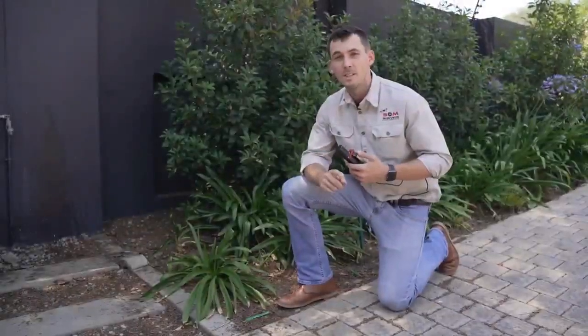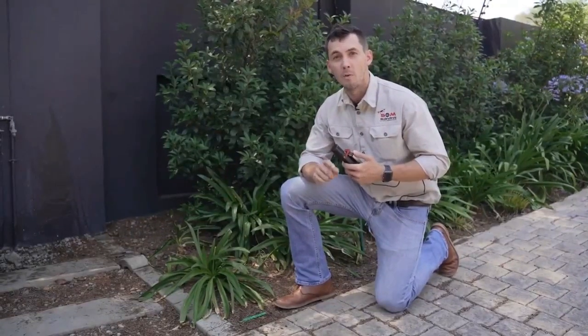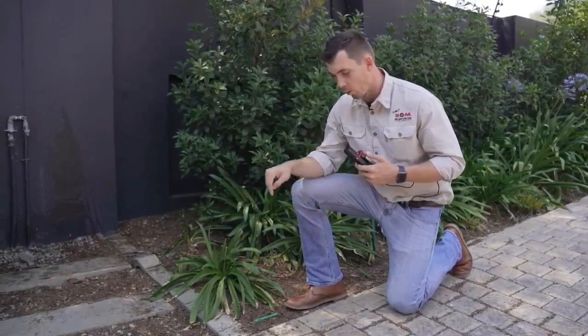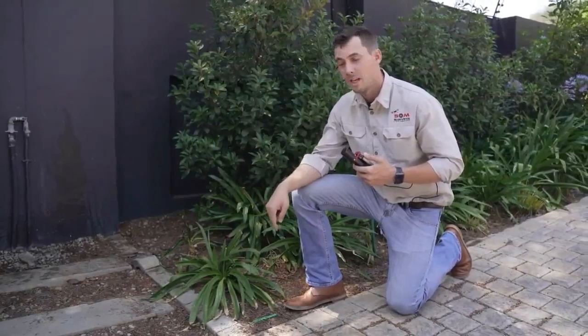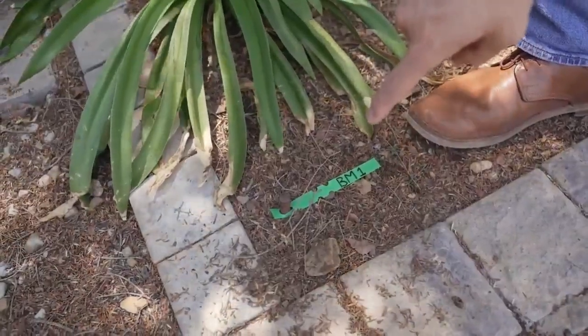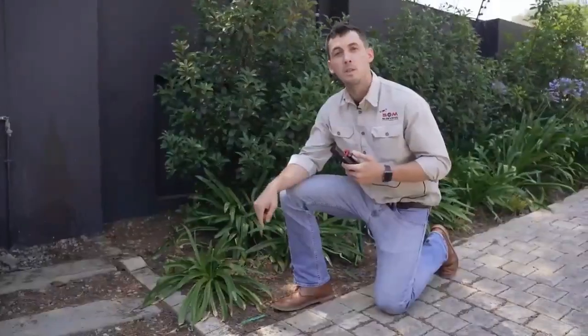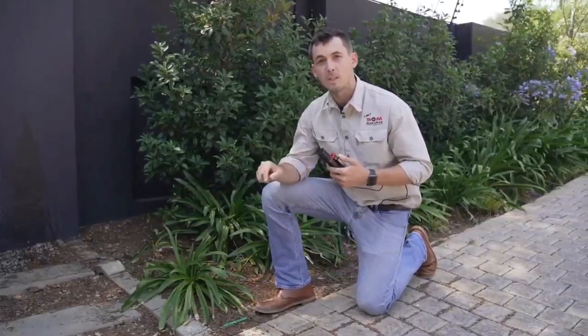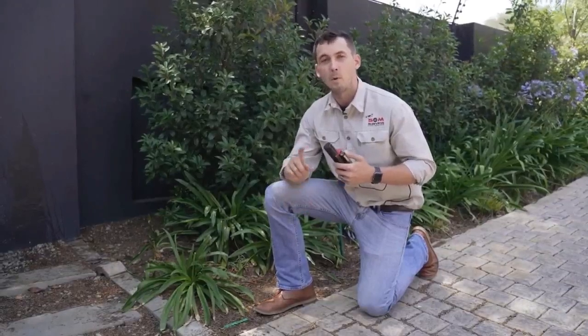The first important step before we start with our task for the day is to make sure that we calibrate or use the existing control on site as what we have found here. This is the original control point which was used to establish and set out this entire building. We're going to make use of that and do a site calibration and make sure that we work from the correct and same coordinate systems.